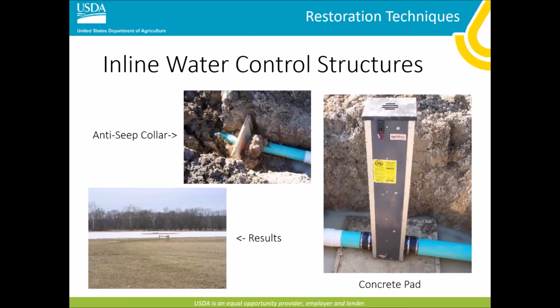Another important aspect is the compaction of the soils around this structure. Really, they need to be done by hand and not construction equipment. This structure that's pictured here is very delicate. A small bump from that excavator or that backhoe could really destroy this structure and make it so you can't even touch those stop logs that are in it. But as you can see from that lower left picture, they do have results. It's amazing what you get when you do stop water on a project site.